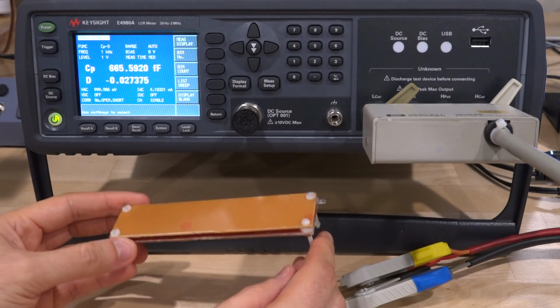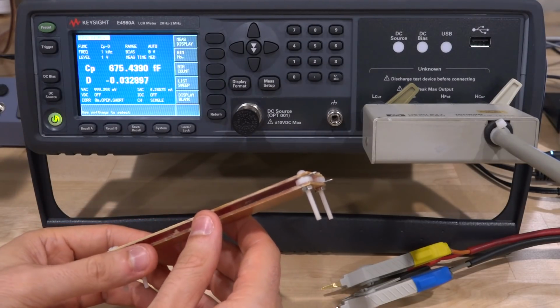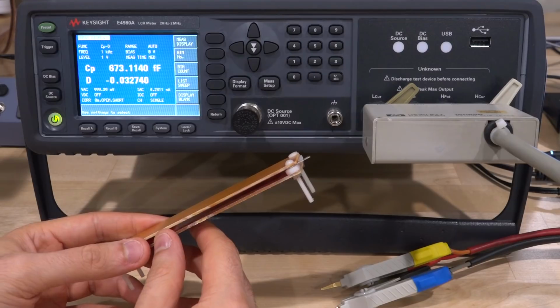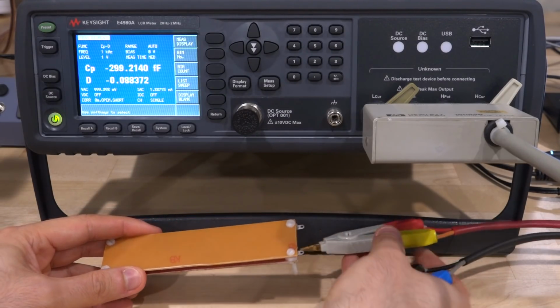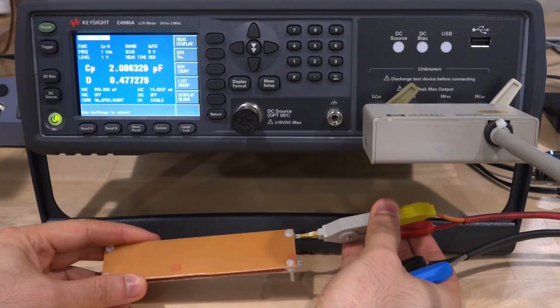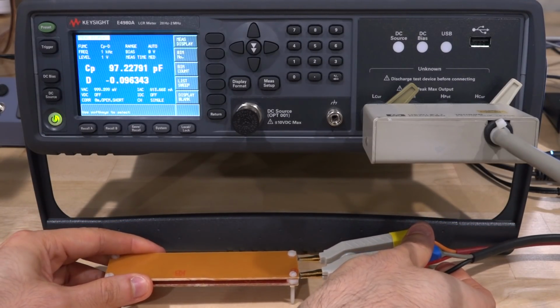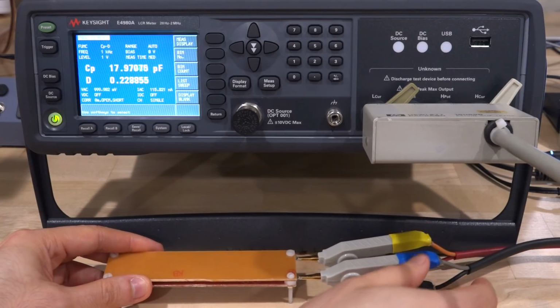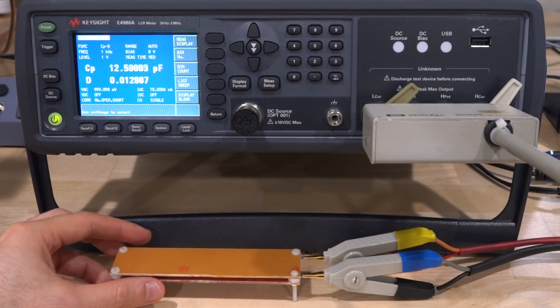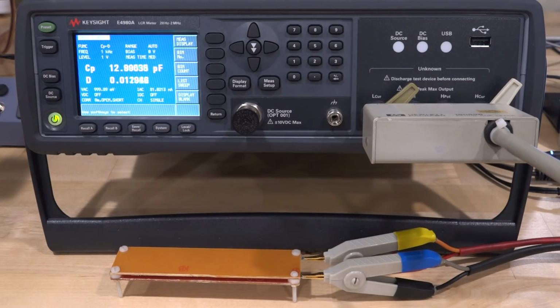So this is 130 millimeters on one side, 30 millimeters on the other side, and the gap is roughly 3.5 millimeters. Now if you calculate that with the epsilon of air in this case and ignore all the other effects, you get a capacitance of about 10 picofarad. So let's measure it, see if it's 10 picofarad or not. Go connect this to here. I've already tried to zero this as much as possible, but let's see what we get. Here we go. Let's make sure it's nice and flat. What do we have here? There you go, 12.9 picofarad.